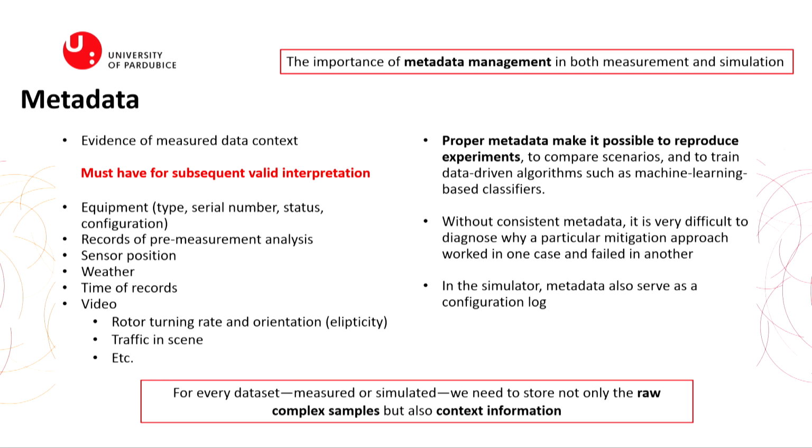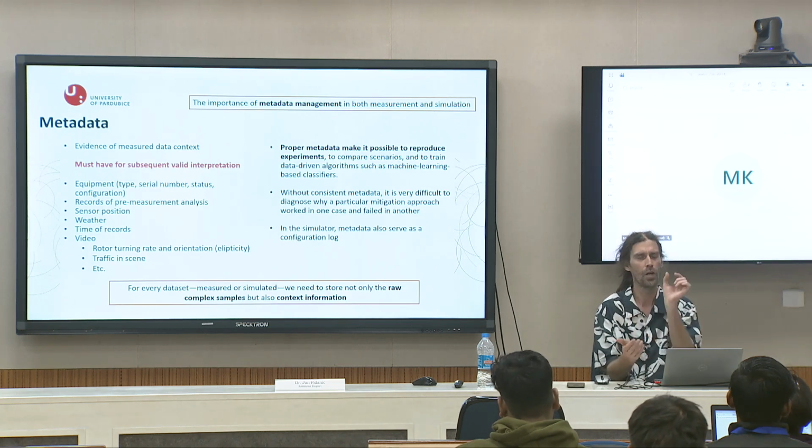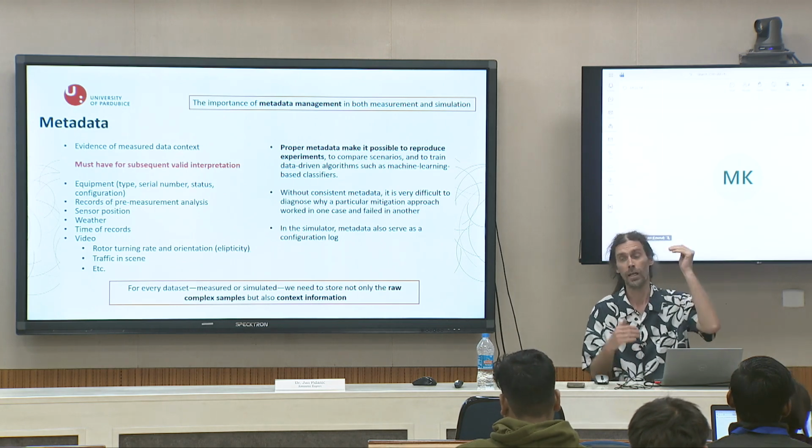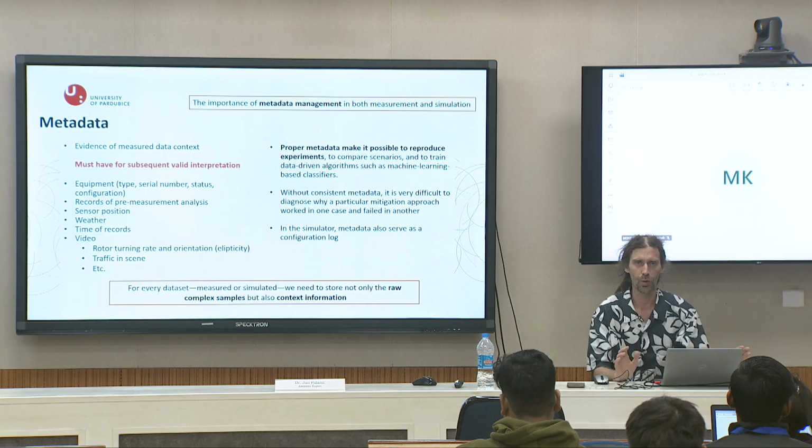You need all possible information about your modeling, log files or measurement, and that is metadata. How you have set your SDR devices, how you have set PRI, PRF, which type of modulation, what was the length of pulse, what was the distance of measurement, and so on.